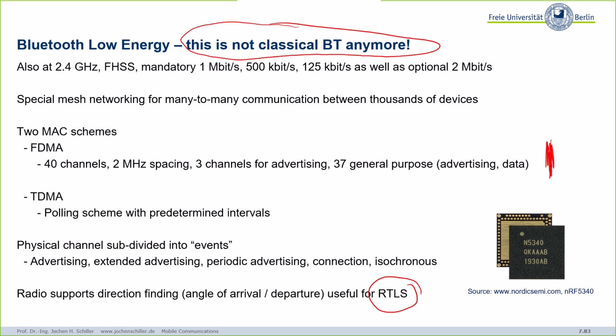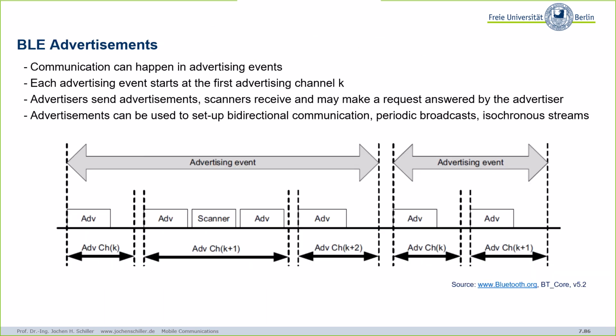Here, Bluetooth Low Energy operates in a different way, where you say, okay, we have so-called events on the physical channel. And what is the most important and the new event? Again, you don't have to remember all these events. It's just the idea. And this is the advertisement. So communication can happen now in advertisements. You don't hear the term pairing first, setting up the connection, etc. No. It's just that you advertise something.